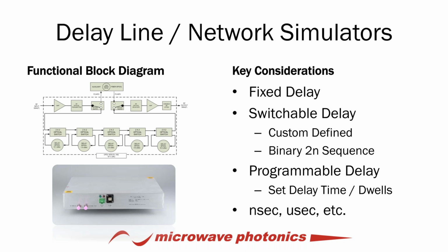The benefit of fiber optics is twofold. One, as I mentioned earlier, you have the ability to impart a uniform loss over frequency through the fiber optic, but also the ability to create delays in very compact small form factor optical delay spools. It could not be achieved effectively by using large coils of fiber cable, especially considering that these delay lines can operate well up to 18, 20, 40 gigahertz.